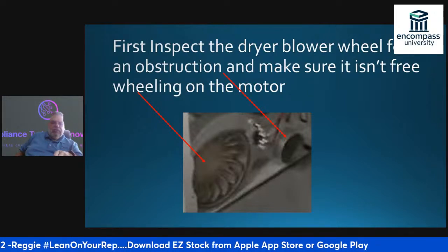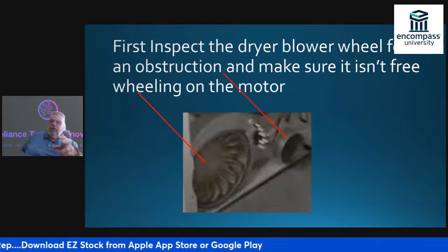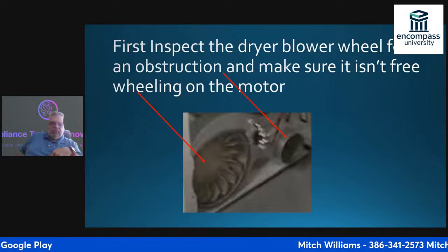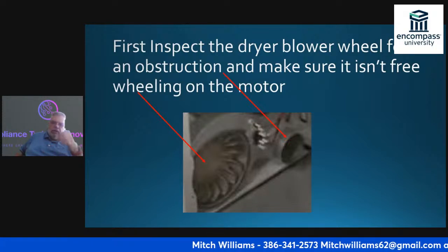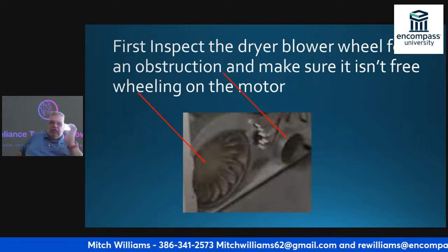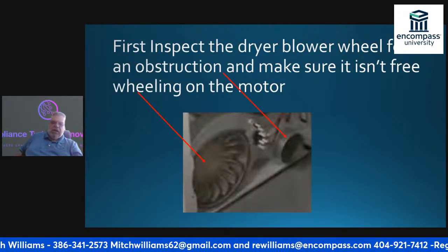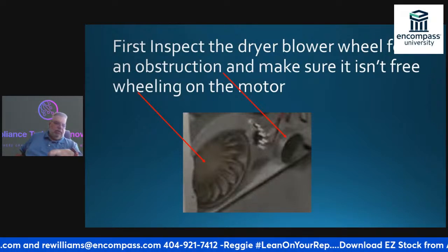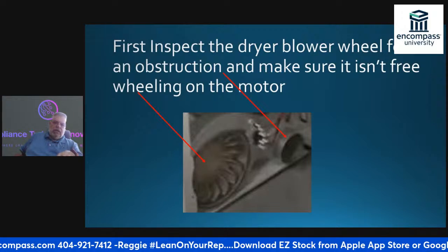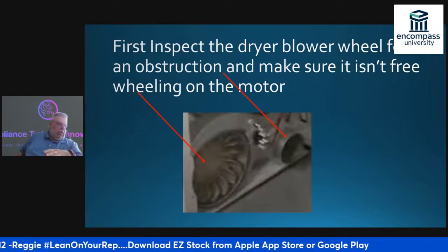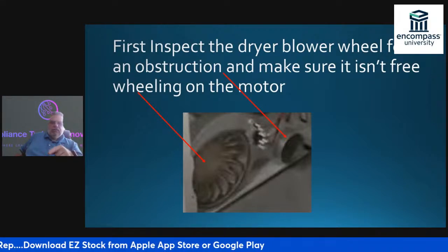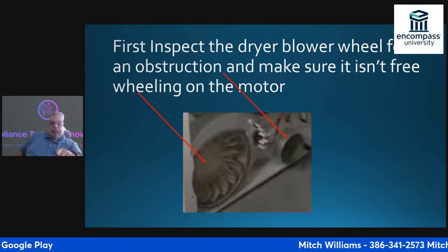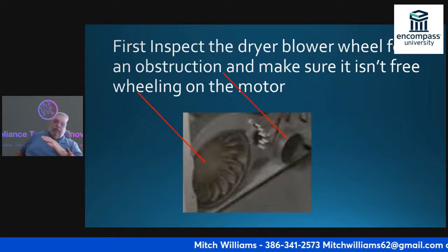I will tell you that I have found, believe it or not, a child's building block. The customer had to have just taken and shoved it down, and then it finally got free and dropped down into the blower wheel. There was enough torque from the motor that it broke the blower wheel. Okay. If that happens, then you have a real problem.